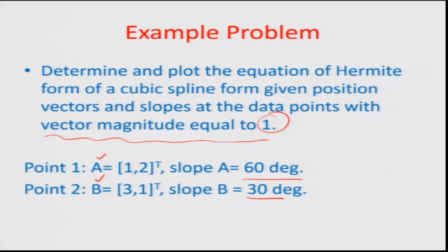So, we have to find out what is the Hermitian fit and generate maybe some tweaking of the end conditions, so that we can have not one curve, but a family of curves, one of which can fit to the profile, and that is what we mean when we talk about curve fitting. Okay. So, in this example we will have to use the cubic polynomial, and try to tweak in a manner so that we find all the unknowns, which is a0 to a3, as I had suggested in the last step, and then putting that value back and putting the equation in place, we should be able to, with the parametric form of the equation, plot for different values of t varying between 0 and 1 the whole curve itself, okay, and then vary something so that the curve varies. So, I think we will do the solution for this problem in the next module.